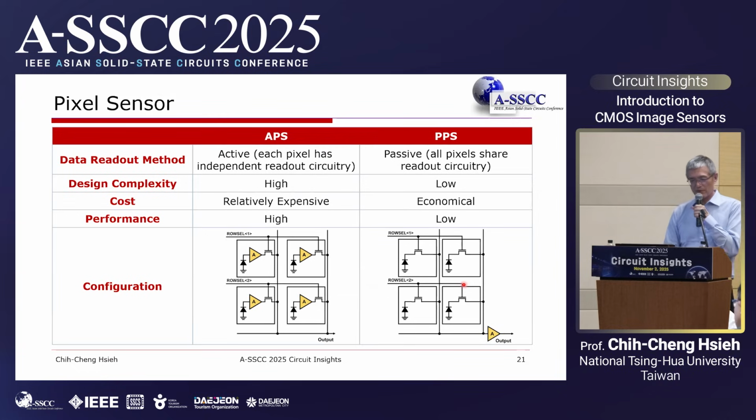So we can do the comparison here: you need some amplification circuit or some buffering circuit to sense the in-pixel voltage and send it out at a readout rate using some active circuit. And when you implement this architecture, we call it active pixel.